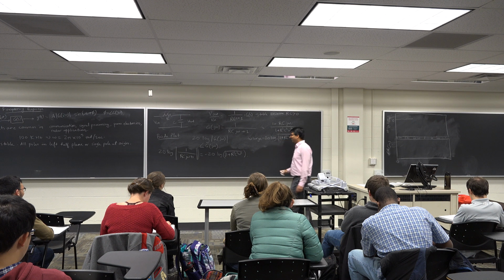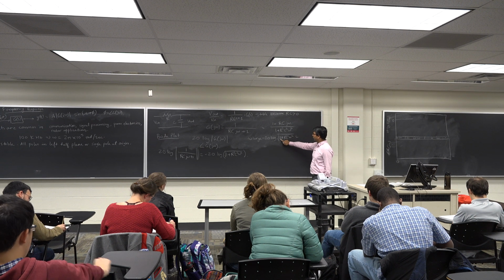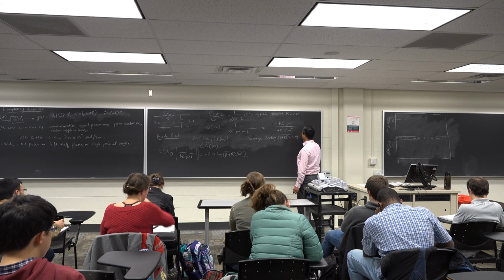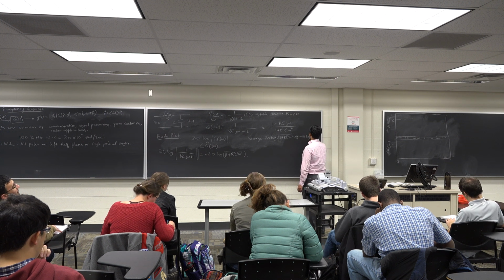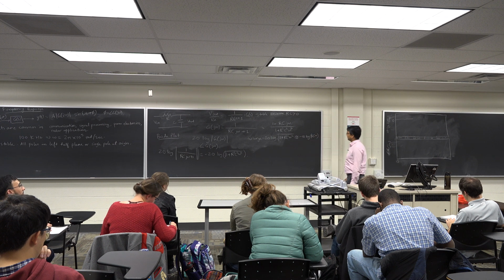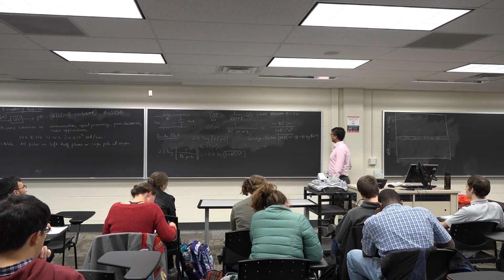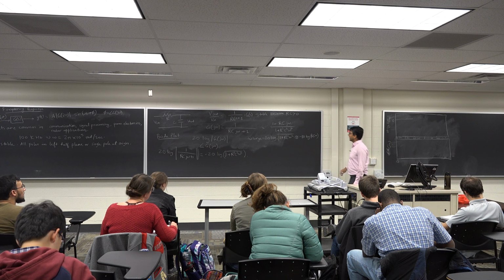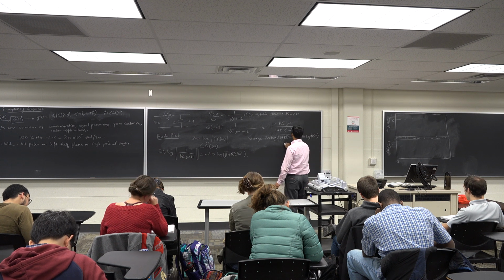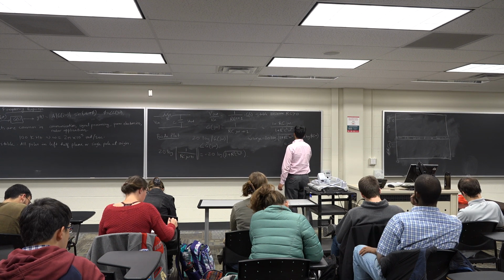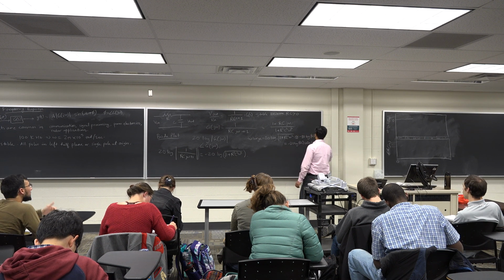Okay, so not very difficult. All right, so when omega is very, very large, I can neglect this term 1 here. So this is approximately equal to minus 20 log RC omega, because there is a square root here. Which is the same as minus 20 log RC minus 20 log omega.